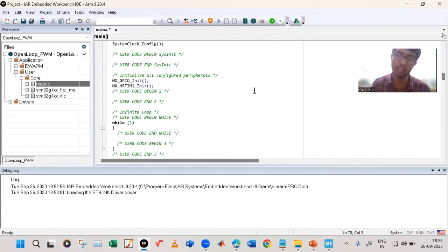That is more complicated. When you're starting out, it is advised to use HAL functions, because at the register level you need to set one bit and reset another bit, and that is not easy for a beginner to understand. You will get lost in it. So there are already-made HAL functions. You use those, and once you have reached a comfortable level of expertise and want to make the code work faster, then you can go to the low level libraries.